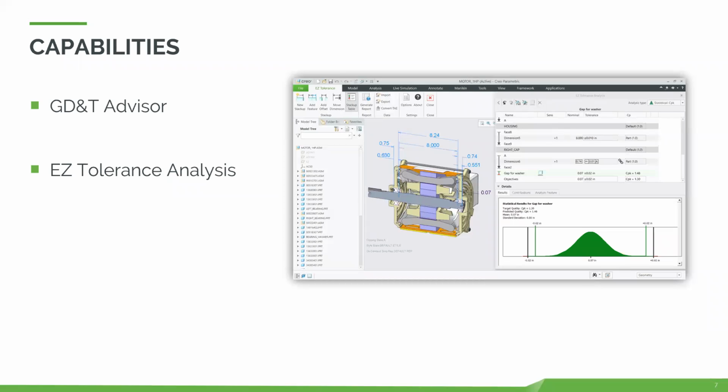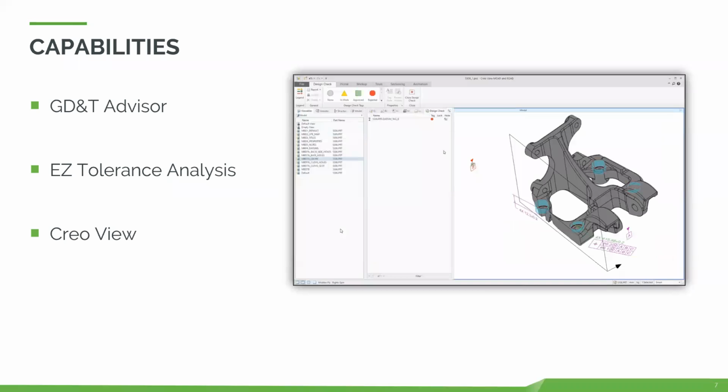prototyping or manufacturing. And we're able to take 3D annotations that you're building out, and you can look into different statistical results, look for potential defects, worst case scenarios, even understanding which of your tolerances are having the highest contribution to the goals that you lay out for the model. So a very powerful tool that we have working around model-based definition for doing tolerance analysis.